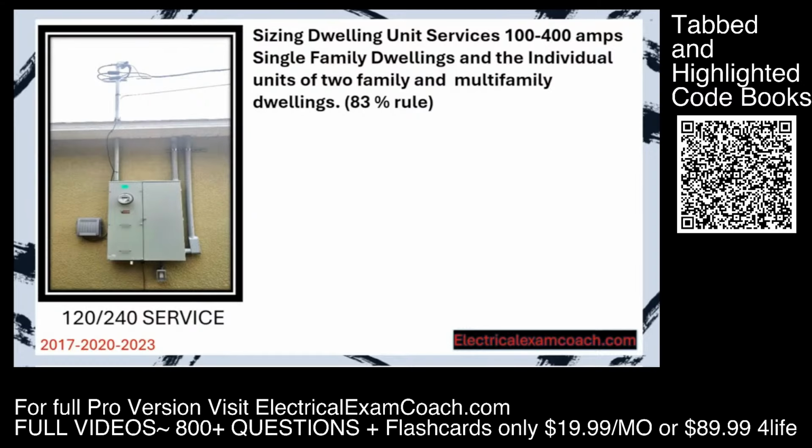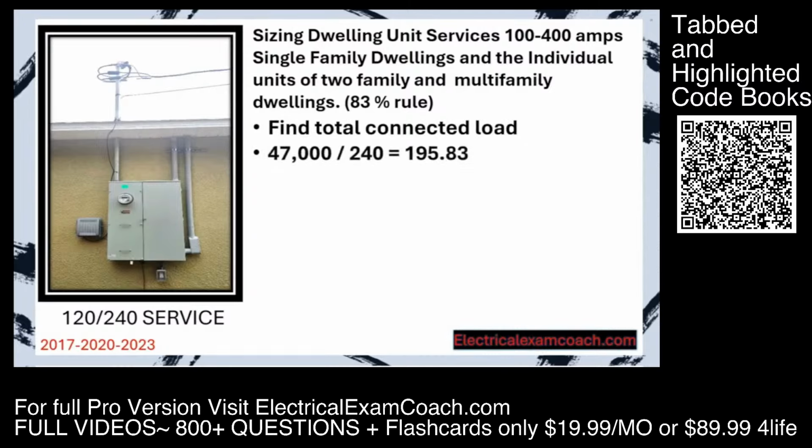Let's imagine that we have a dwelling, and the first thing we're going to do is find our total connected load. Let's imagine it's 47,000 VA on a 240 volt system. That gives us 195.83. We would round up to 196 and go size our main breaker. The main breaker would be a 200, that's the next standard size. We now have a 200 amp service.